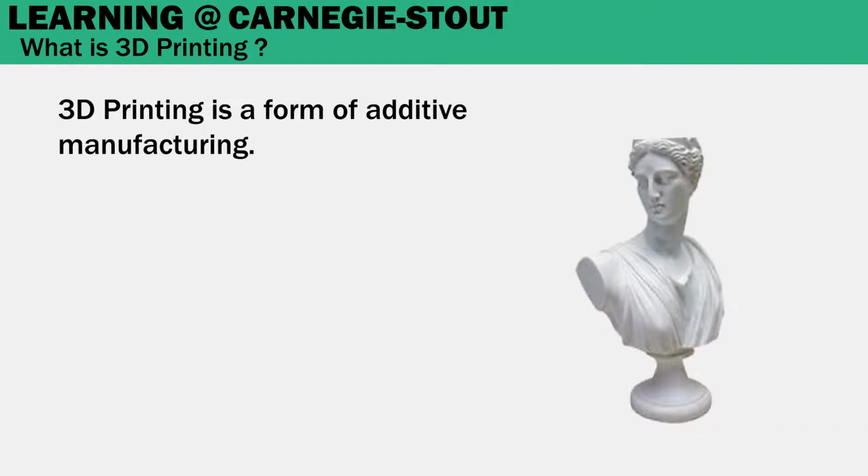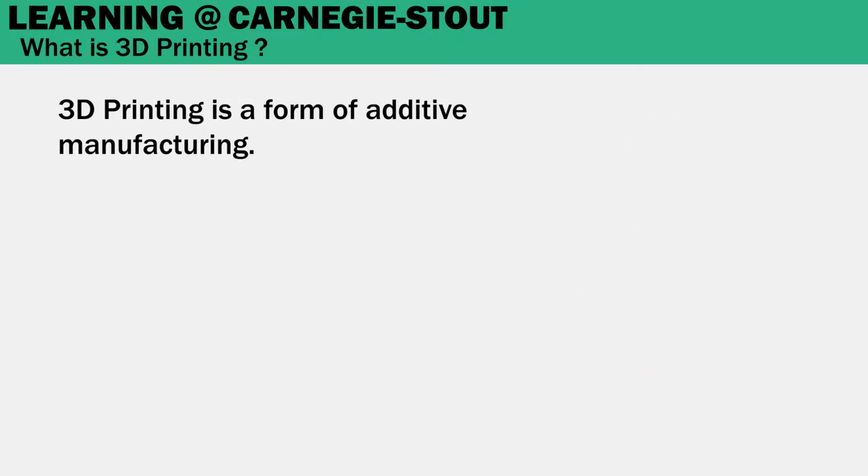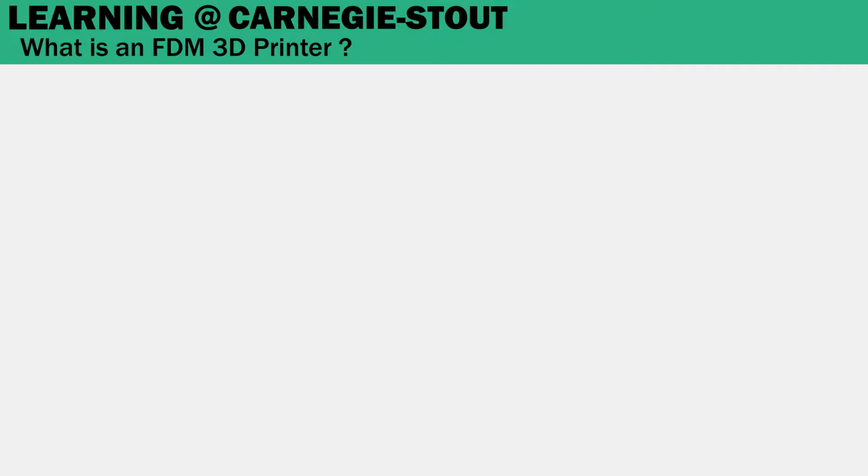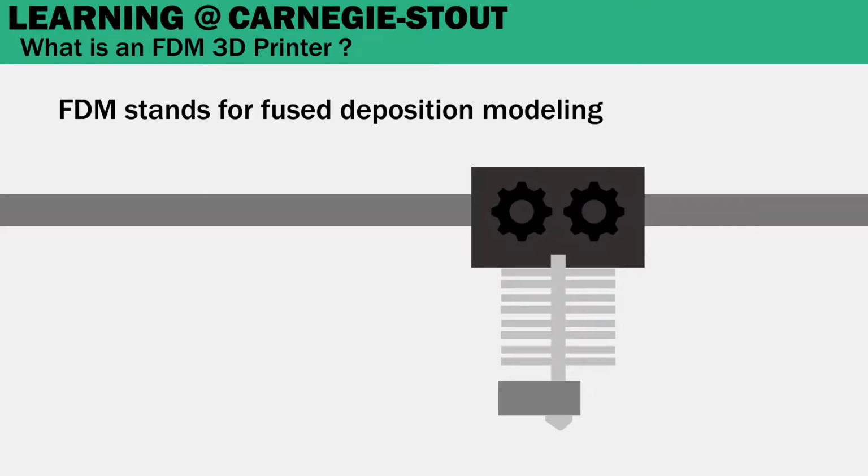Only these little bits that 3D printers create with are not chunks of rock, but are instead thin layers of plastic, fractions of a millimeter in height, called layers. These layers are the basics of 3D printing, specifically FDM printing. What is FDM printing? FDM printing stands for Fused Deposition Modeling, and you can kind of break that down to figure out what it means exactly. So you're taking your deposits that you're printing with and fusing them together to create your model. With this type of printing, we are fusing multiple layers of plastic to make a model.